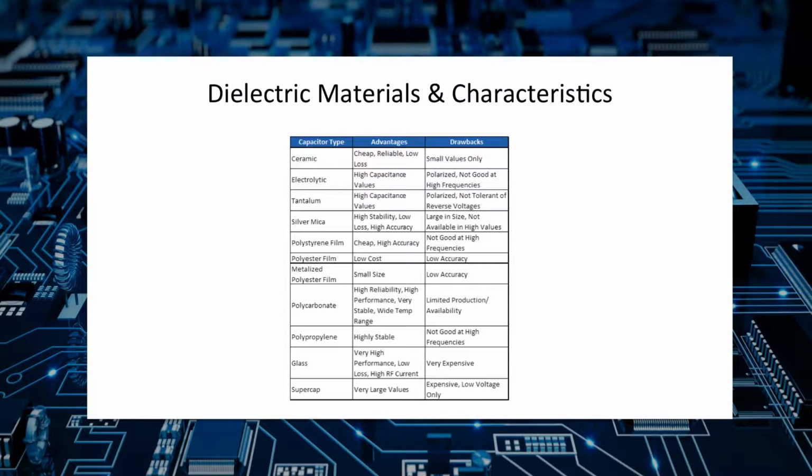For example, electrolytic capacitors offer much higher capacitor values for a given size, but also exhibit higher leakage and lower reliability than other types of capacitors. Electrolytic capacitors also tend to fail catastrophically, and they break down over time. In fact, I'm currently restoring a Commodore 128 computer that's about 30 years old, and as part of that restoration, I'll replace all of the electrolytic capacitors just to ensure that they don't fail.